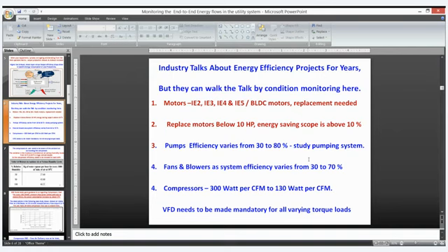It is not an instant measurement, it is a trend measurement. A compressor is basically a dynamic process variable, and it keeps changing dynamically. So it needs to be monitored for delivery pressure, delivery temperature and delivery flow. The compressor's delivery flow for the given rated pressure and temperature matters more for us.